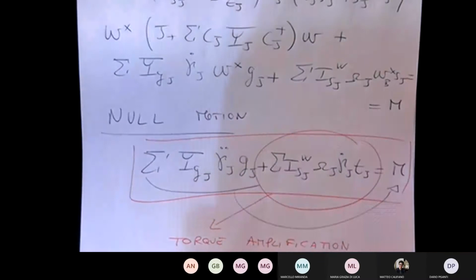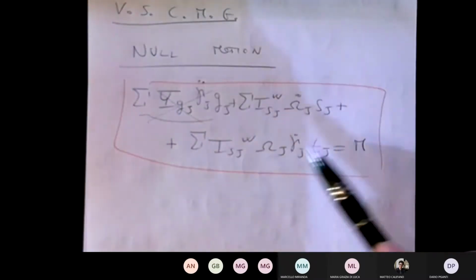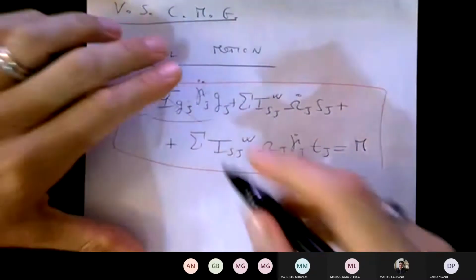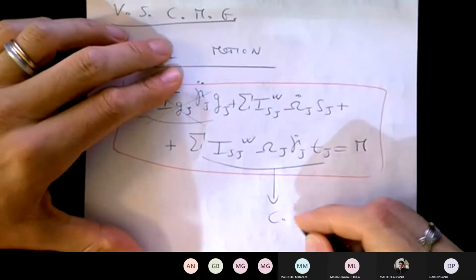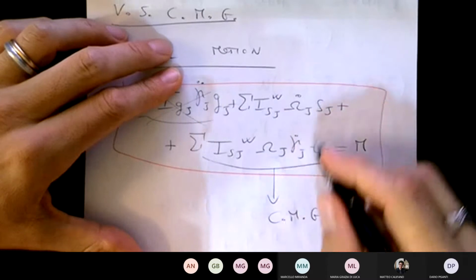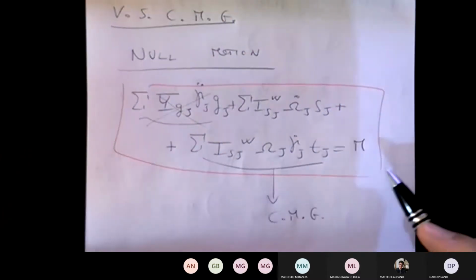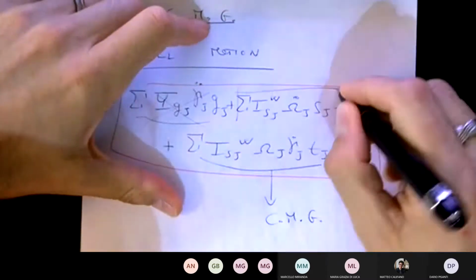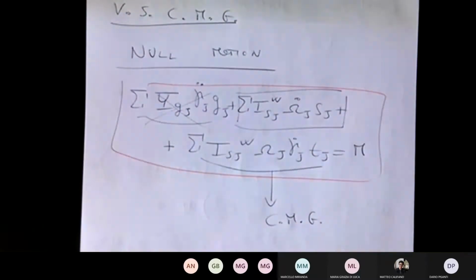And so there are additional constraints to the design of the control law that can try to handle the problem of singularity. But the beauty of VSCMGs would be that, well, this is the CMG term, right? If this is for some geometrical reason not able to give me the torque I want, I don't care. I have the reaction wheel term. So basically, variable speed control moment gyros are nothing more than combining CMGs and reaction wheels. As I said, to my knowledge, they've never been used in space, because if CMGs are difficult to control and complicated, these are even more complicated.